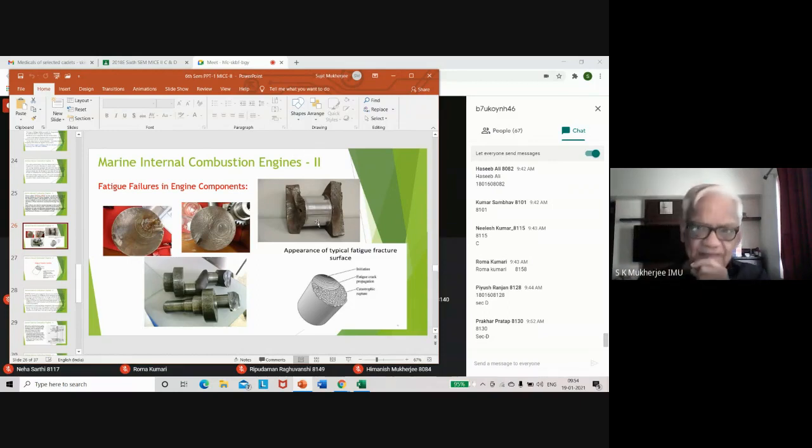Similarly, here, this side breakage has taken place because this side has failed. If one side fails, the other side gets the full load, which it cannot take. So it is broken. And see, this particular one has broken from where the oil hole is. This is the weakest part of the material. It is not in continuity. So that is why it has failed.